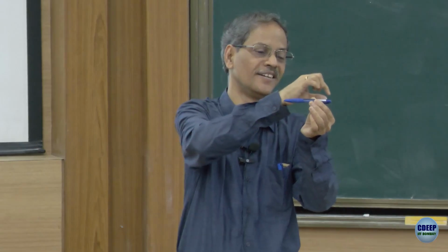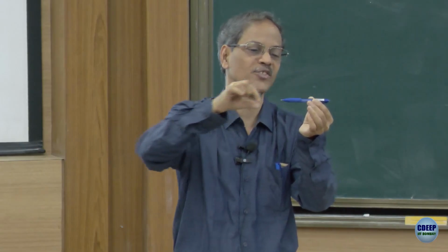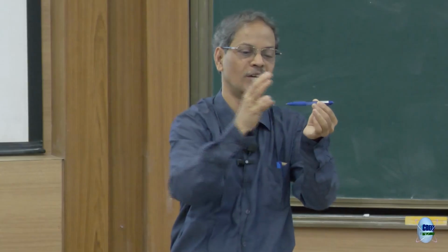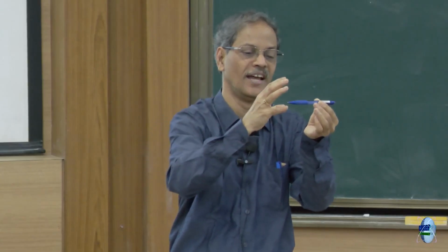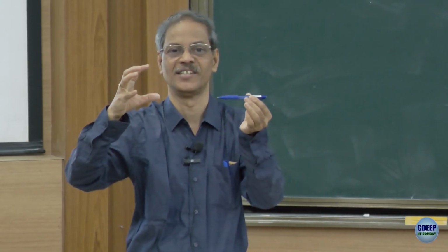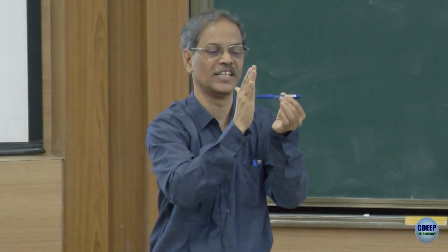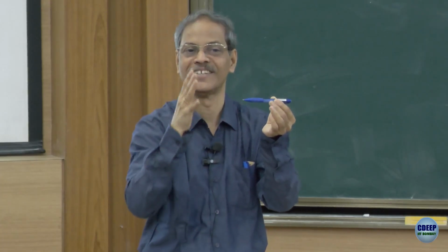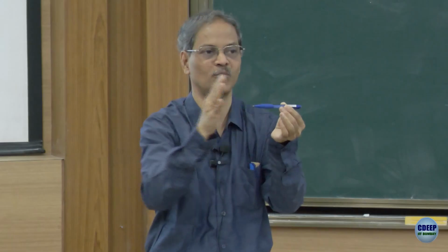We assumed that this rod is made up of millions of longitudinal fibers, and when I apply a load or pull, all of these fibers move together. So, if this was a cross section here, after deformation it would have moved here, the entire cross section remains the same, it just parallelly moves like this.